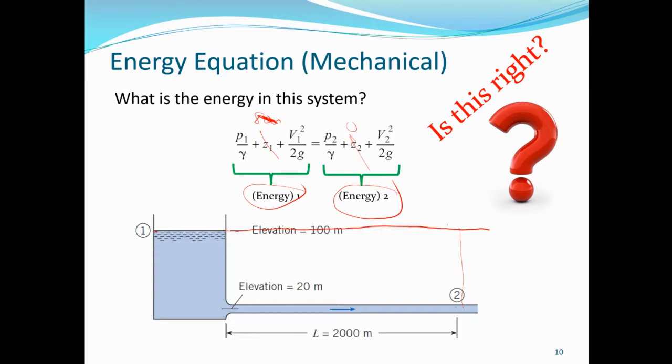But as we are going to see later, there is loss of head. It is expected that if it remains constant, when you put a piezometer at this point, water will rise up to this level, isn't it? But in the real case, it will not rise up to this level. Maybe it will rise up to maybe this level, let's say. Then what happens, why the difference? It means it has dropped, from this to that level.